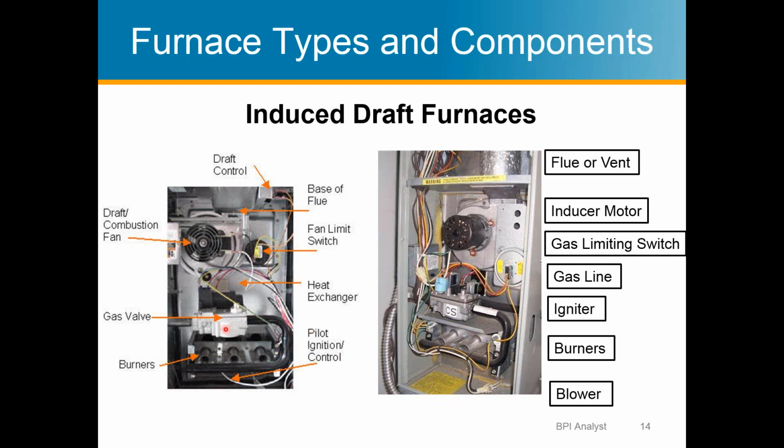But you open this door, turn it on, and on these units there's typically a glow plug, just like in a diesel engine where there's no spark plug. It'll start glowing bright red, and there's a temperature sensor next to it so that the computer knows it's ready.